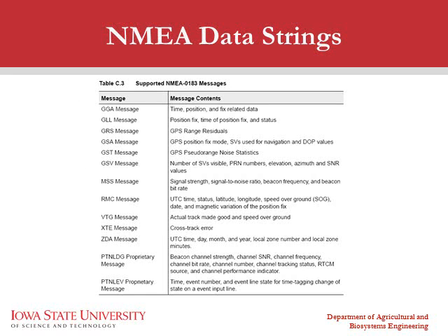There are a variety of different GPS data strings that are available from a GPS receiver. These are standardized under the indicator of NMEA, so these are typically called NMEA GPS data strings. Each of the data strings begins with an indicator that tells us what type of message it is.